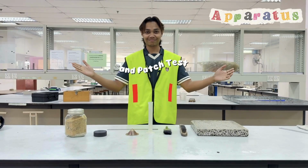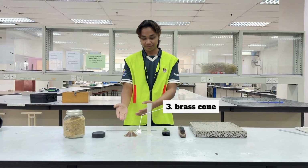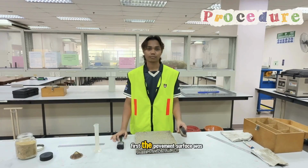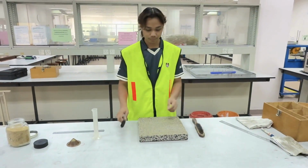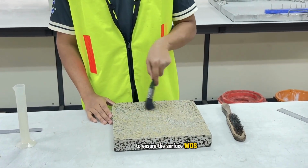The apparatus of the study include Ottawa sand, sand spreading tool, brush cone, a ruler, measuring cylinder, soft brush and wire brush, and also the pavement surface. First, the pavement surface was cleaned with a steel wire brush to remove dirt and loose materials, followed by cleaning with a soft bristle brush to ensure the surface was clean and dry.